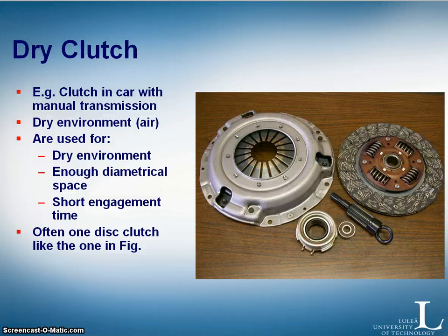So a dry clutch then. As I said, a dry clutch can be used in a car with a manual transmission. A dry clutch normally works in air. It could also work in other gases, but the simplest is always to have it working in pure air. Dry clutches are used for dry environments, and where we have enough diametrical space, because we need quite a large diameter, since we normally only have one clutch disc in dry clutches.